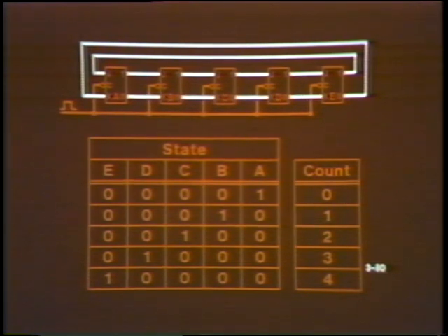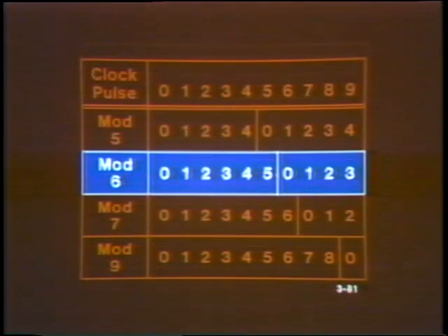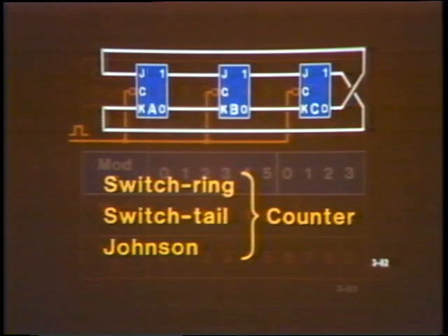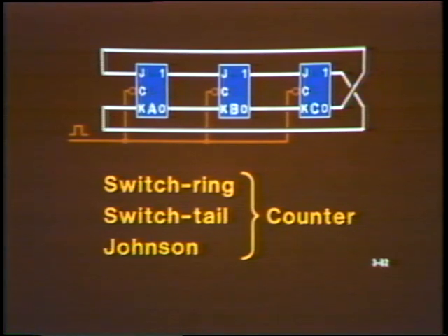There are other designs for modulo 5 counters. We'll examine one of them later in the workbook. Right now, though, let's turn our attention to modulo 6 counters. Here's an interesting variant of the ring counter. It's known by several names: switch ring, switch tail, or Johnson counter.